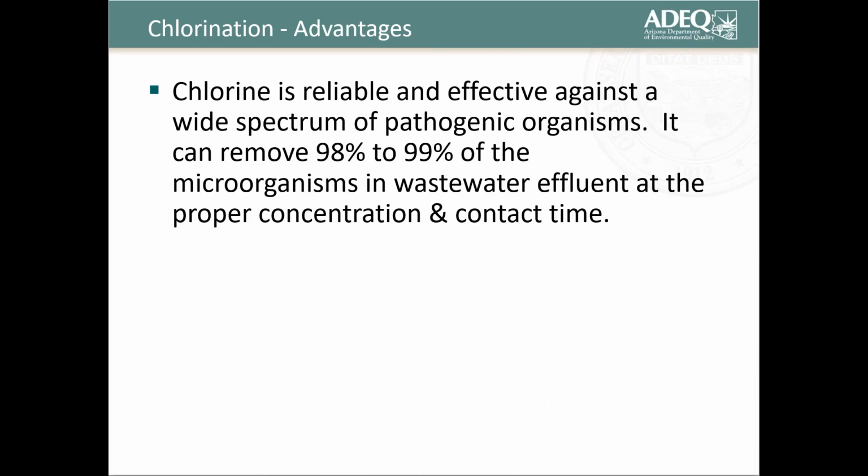Now let's consider some advantages of why it's such a good idea to use chlorination. Chlorine is reliable and effective against a wide spectrum of pathogenic organisms. It can remove 98 to 99% of the microorganisms in wastewater effluent at, note this, the proper concentration and contact time. Both of those go together.